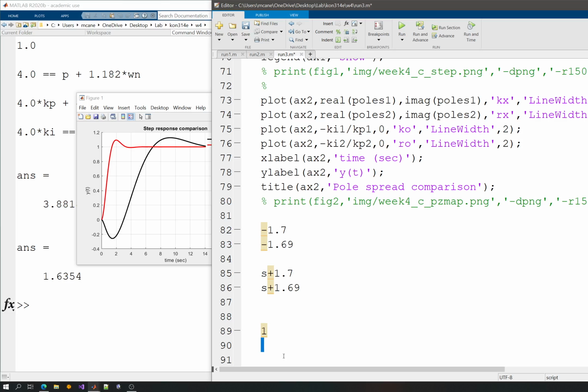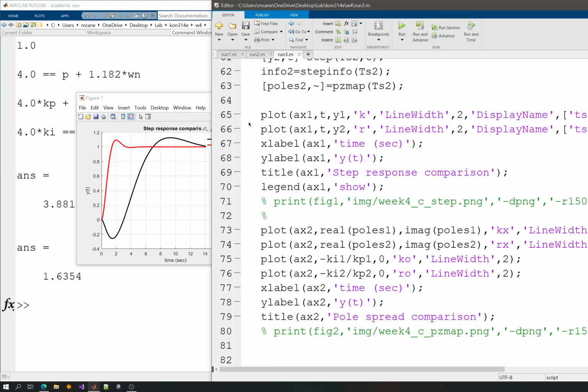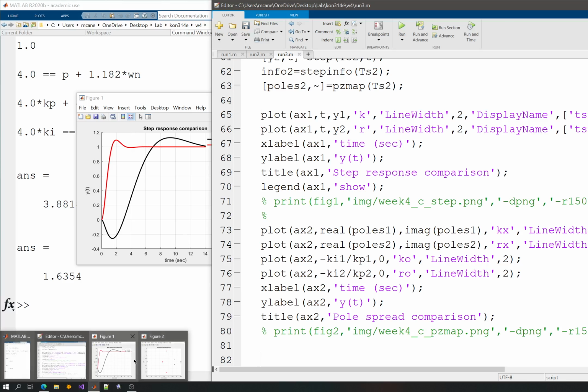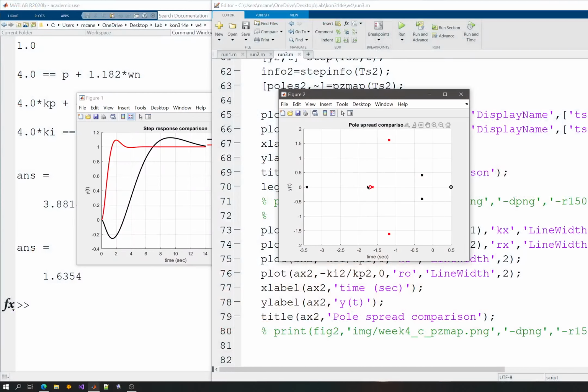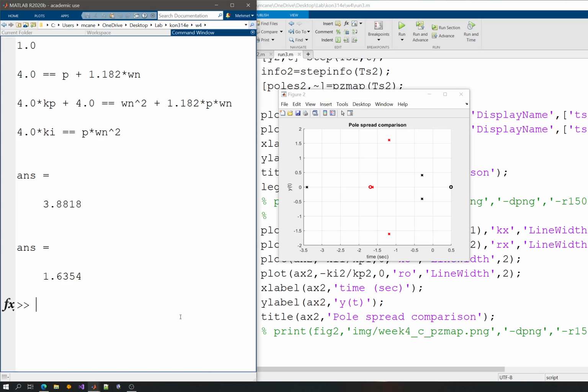So now, enough talk here. You can now see that the zero and the pole for the setting or where we have red are very close to each other. So this is a pole zero cancellation, and if we have a pole zero cancellation, we will be happy. Especially for high order systems, because the system automatically will decrease in degree, since you are placing the zeros such that your third order system will become a second order system. And we can see that here.